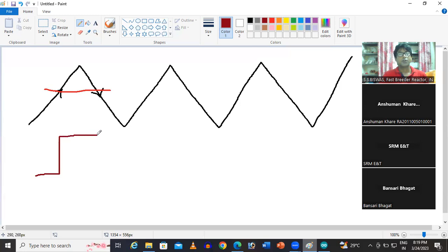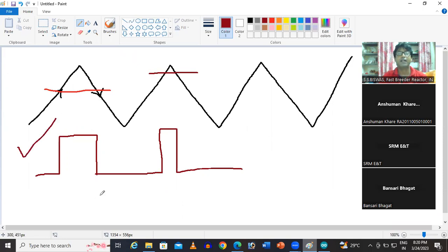When it matches while down counting, it will reset like this. Similarly, say here the compare register value is this one. Here it will match, then it will go high, keep on, then here it will fall like this. This is called phase correct mode. And as I said, that particular channel setting 11 makes this pulse a non-inverting PWM.